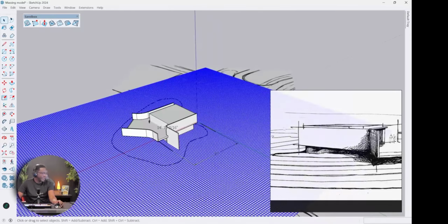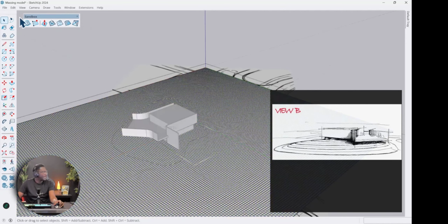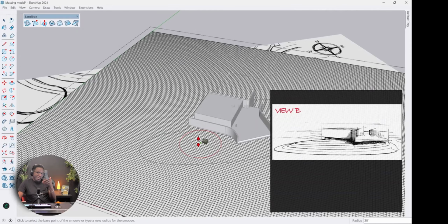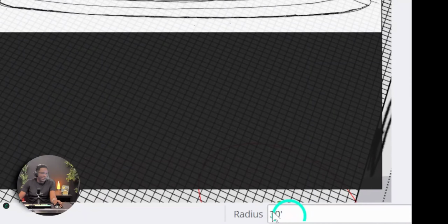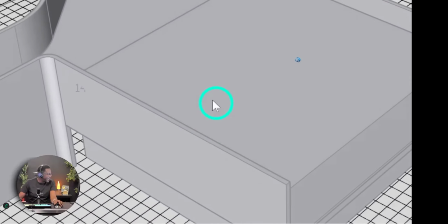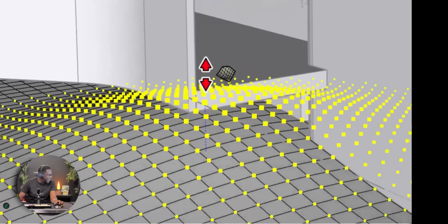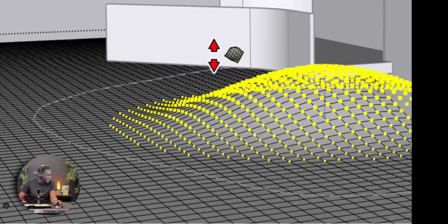Now, to get the hill created, and we're talking about this little hill right there, we're going to double click and we are going to use the smooth tool. Notice you'll get a little radius here to illustrate where it's going to rise up. And what we want to do is maybe increase the radius of this. So right now it's 30, so let's make it about 50 feet. So now it's a little bigger. And notice we can't really see the areas here, but that's okay. We can maybe go right here. And then what we're going to do is click once and move this hill upward. And you can see where it starts to create that mound up here.